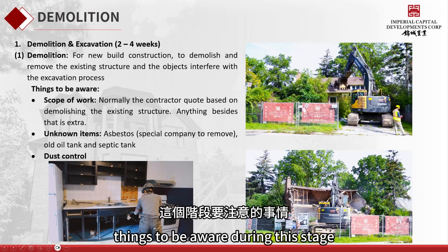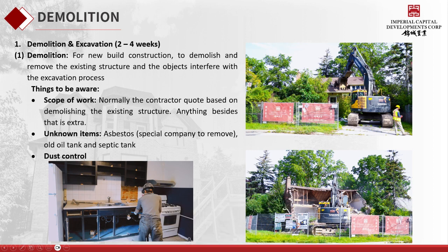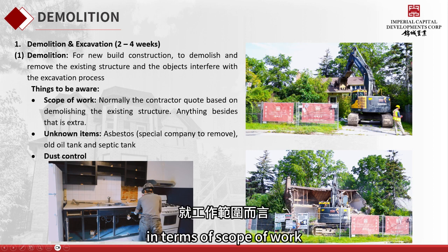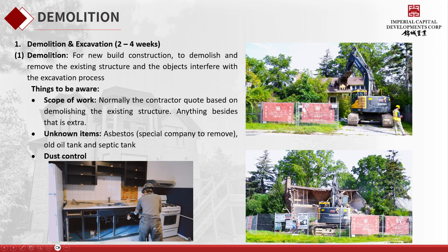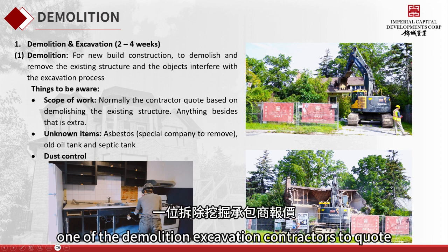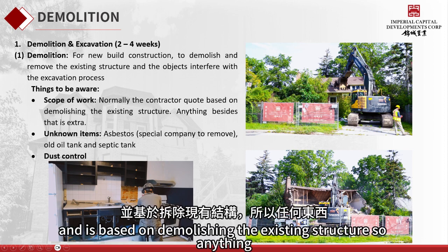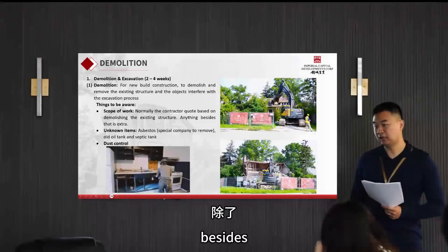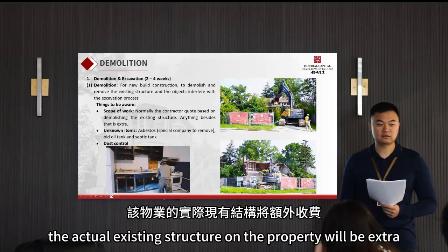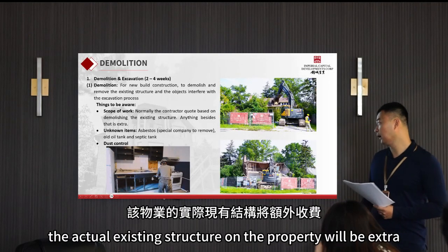Things to be aware of during this stage. In terms of the scope of work, when the demolition and excavation contractor quotes the project, it is based on the drawing and on demolishing the existing structure. So anything besides the actual existing structure on the property will be extra.